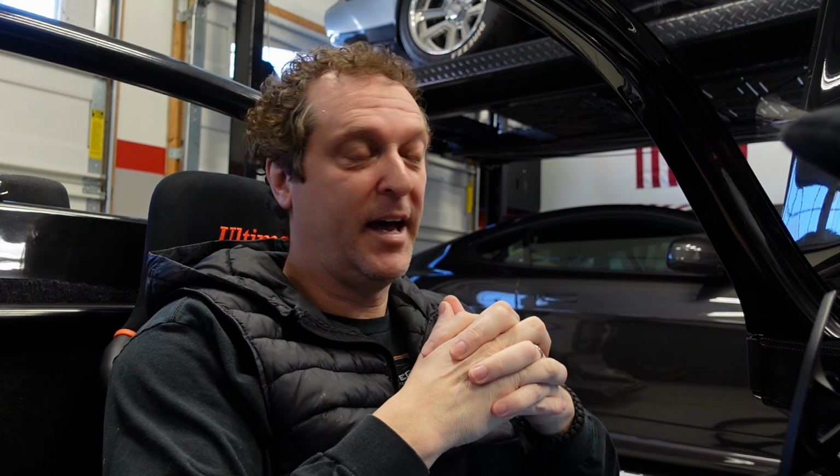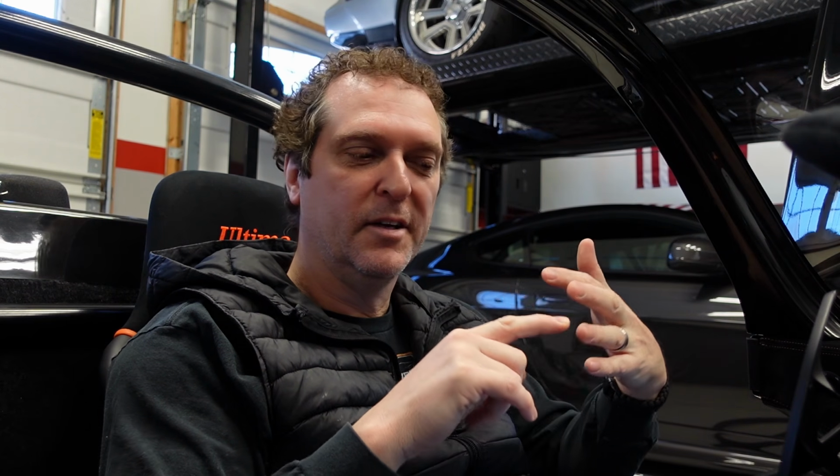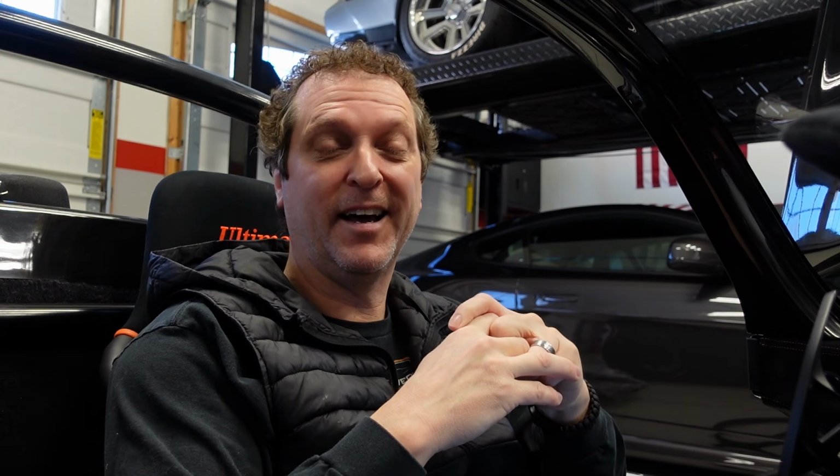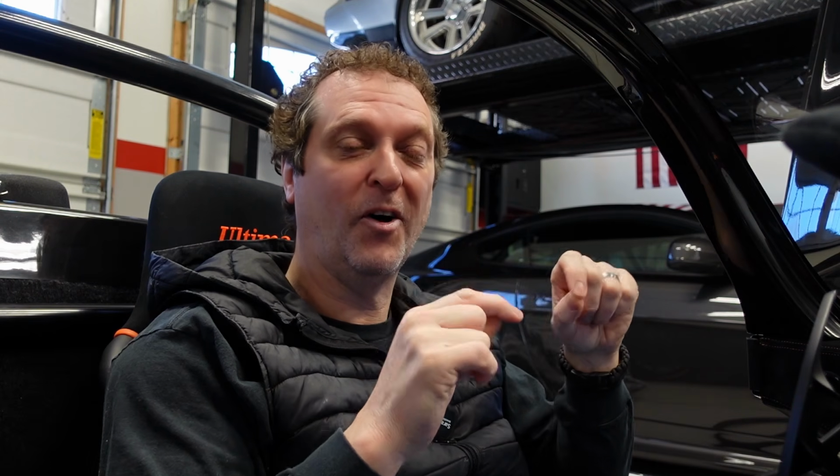Now, the other reason we started with brake switches, I've learned that some of these manufacturers are combining critical elements together. So engine speed or RPM, brake switch, throttle position, those are typically grouped together on the same CAN ID. You notice I mentioned RPM, so we now have a clue. It could be that CAN ID number 105 also includes RPM as well, not only brake switch and throttle position.